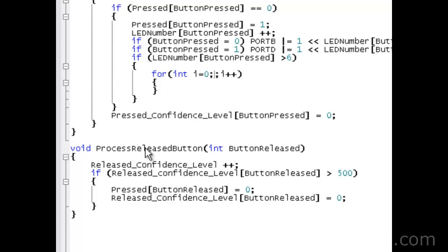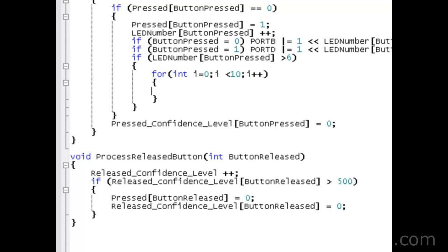And then we have to have a condition. This will be alive as long as this condition is true. So I'm going to say as long as i is less than 10, continue to loop and perform these particular instructions. I'm going to work with only one port right now, just to make things easier. So I'm just going to have this port blink on and off, and I'm going to have a 10 millisecond blink between them. That's why we kept the delay.